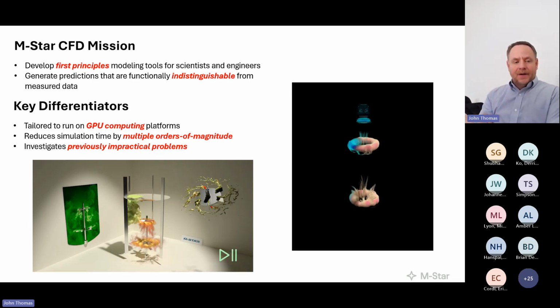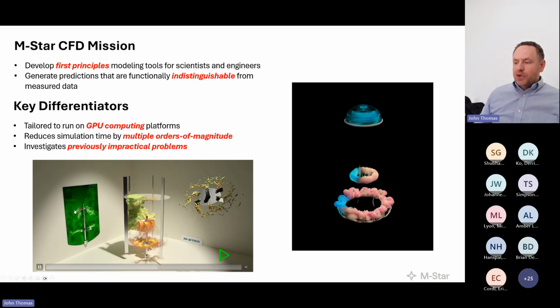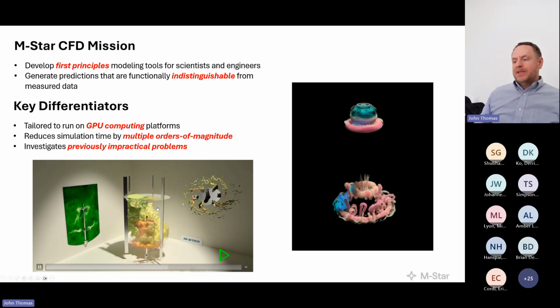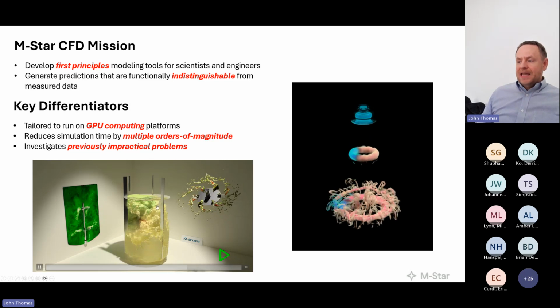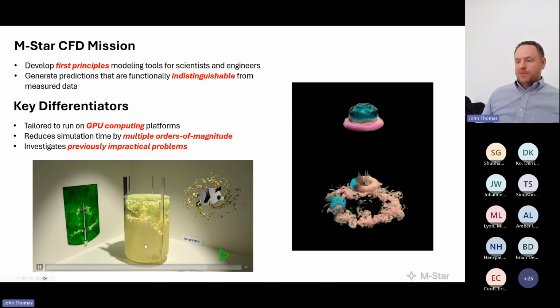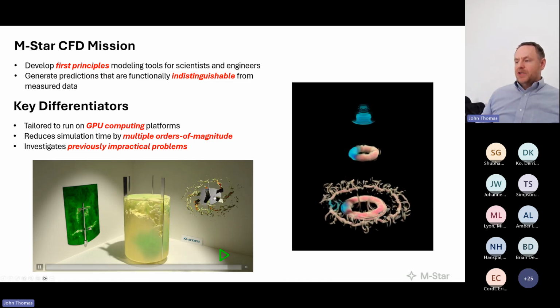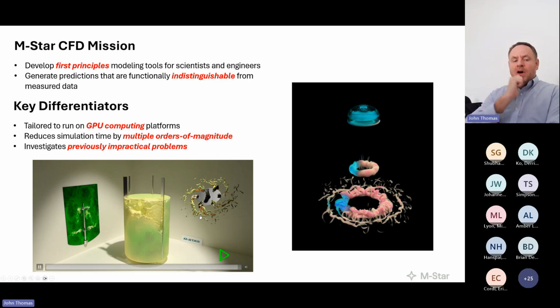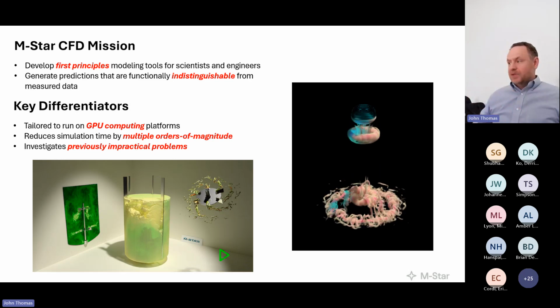Importantly, what we're predicting here is directly analogous to what you'd see or measure inside the lab in terms of the time evolution of the velocity field, or perhaps the time evolution of the concentration of the species as it homogenizes through the tank, and comparing how the conductivity, for example, varies across three different probes as they converge towards a well-stirred state. Or if we have some PIV measurements trying to characterize EDR or shear in a trailing vortex, we want to predict data as it evolves in real time.